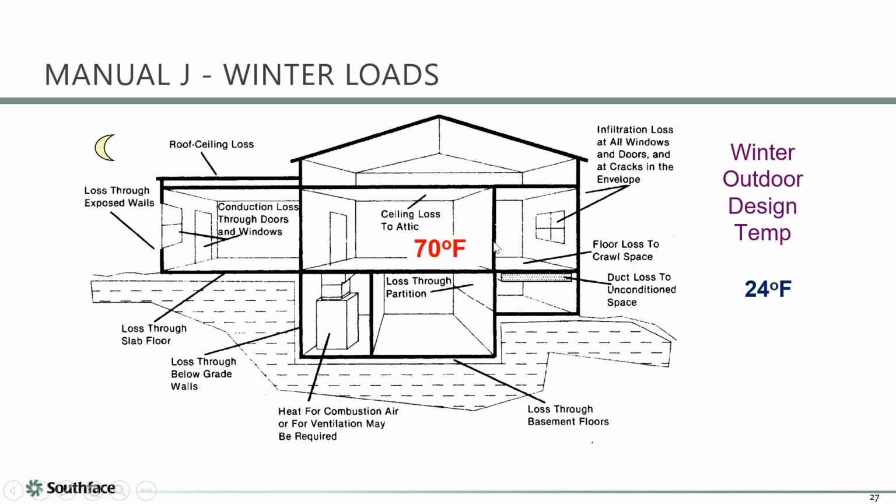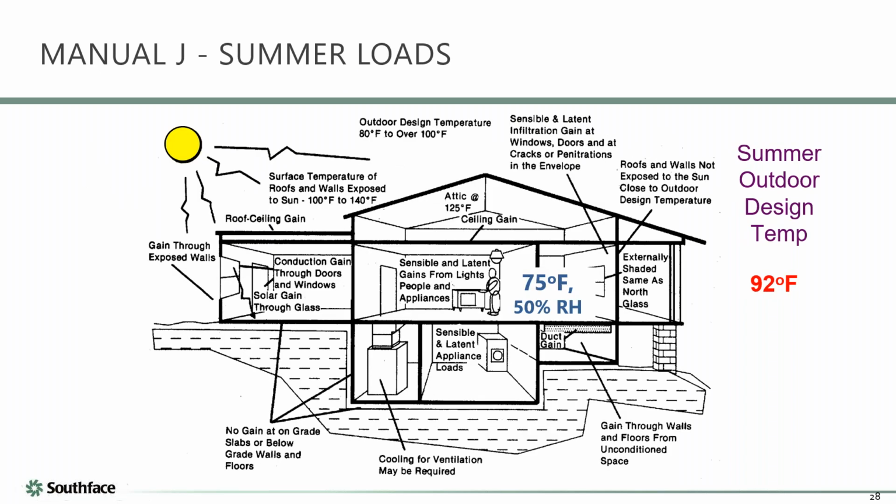At nighttime, we have no solar gain. So that's why we calculate the heating load at nighttime. We have no solar gain, and we do effectively UA delta T, and there's the delta T across the walls, the floors, the ceilings. We account for infiltration. We account for where the ducts are, a few other little things, and we completely ignore all the internal gains. So worst case, we are really a worst case load calc in the wintertime. So that's basically what comes up with our winter load.